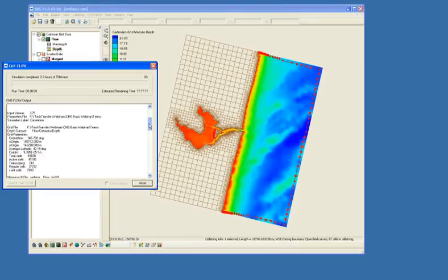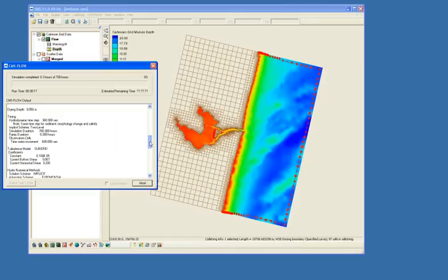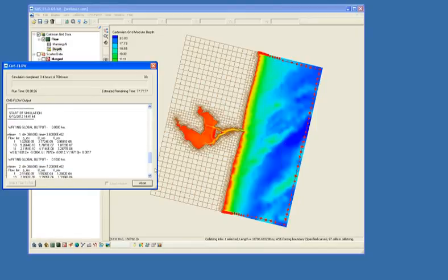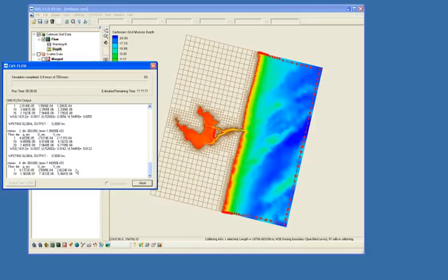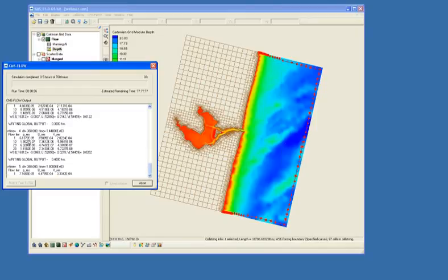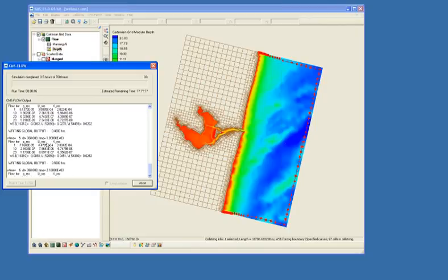There's information about how the file was set up, parameters, what processes are turned on, the time steps, how many processors are used. And then as it's running, there's more information about it writing information out every 0.1 hours, it looks like, giving residual information on pressures, U's and V's. This is diagnostic information, so you can see how well it's running.